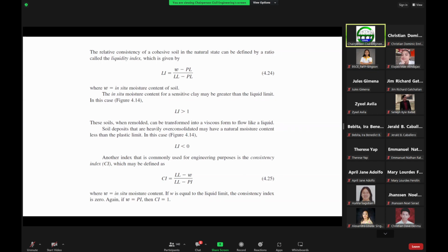So that's why during geotechnical investigations, I am very strict in the measurement of the groundwater level in the field. Normally I ask our drillers to measure the groundwater level from the start of the drilling works until we finish, to see if there are changes with time.